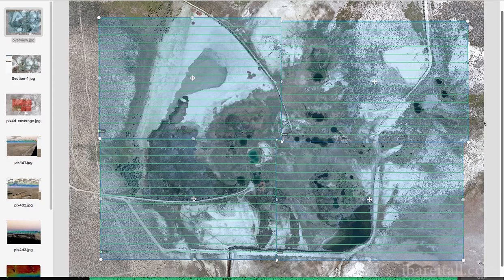So basically I had 4 sections, and this is photoshopped together to show you the area that we did. I would fly one section, which took about 22 minutes to capture, and the drone follows a certain path in a grid and takes photos pointing down. You probably want to make sure you don't have any weird overcast or clouds, because then you're going to get some photos that might have shadows in them or moving shadows. So try to find a good day, not too bright.